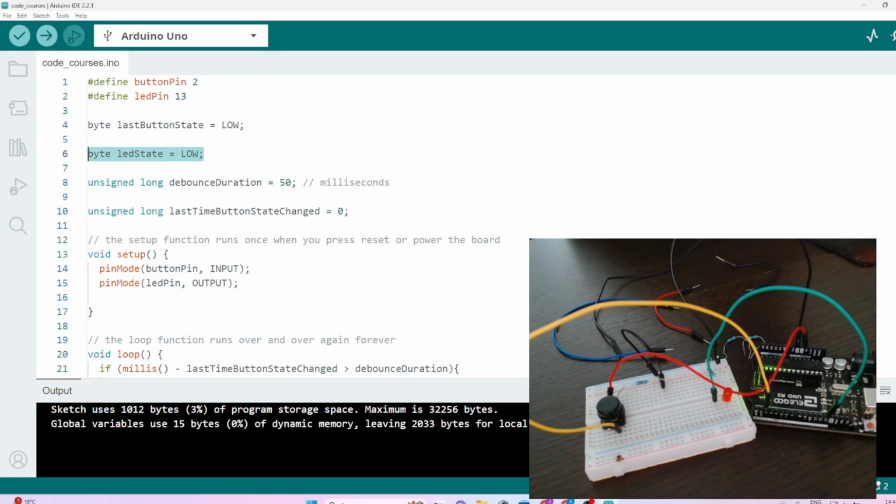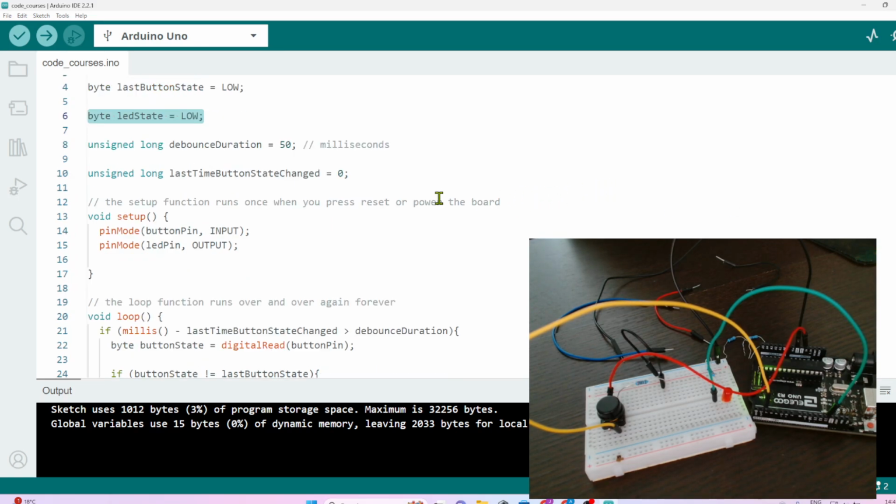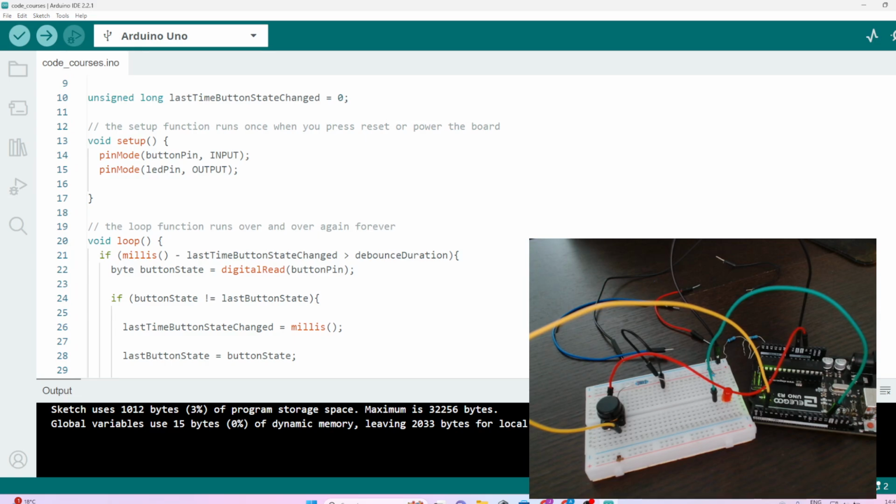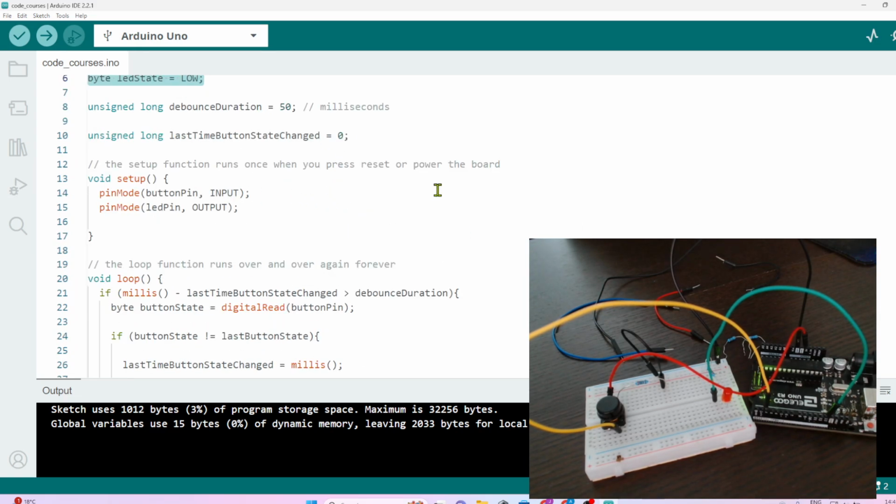After that, we need to assign a time for our circuit to catch the button state, so that, for example, when a mechanical button is pressed, it doesn't switch cleanly for a few milliseconds.